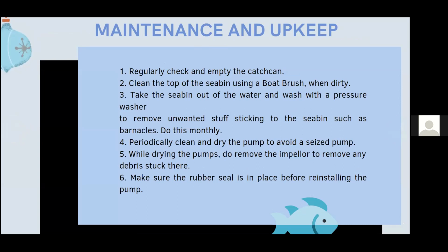Advisably do this monthly. Periodically clean and dry the pump to avoid a seized pump. While doing that, do remove the impeller to remove any debris stuck there. Make sure the rubber seal is in place before reinstalling the pump and putting the Seabin back in the water.